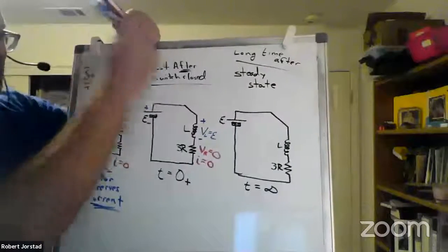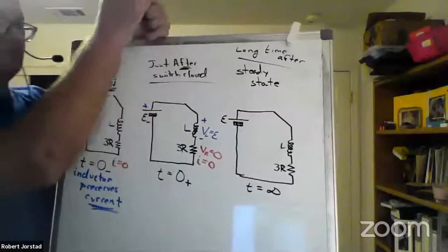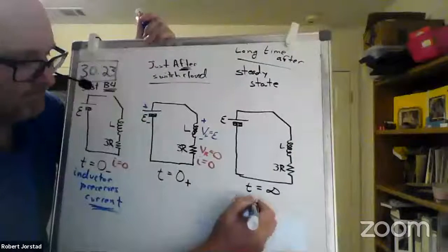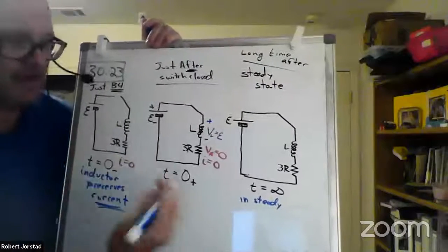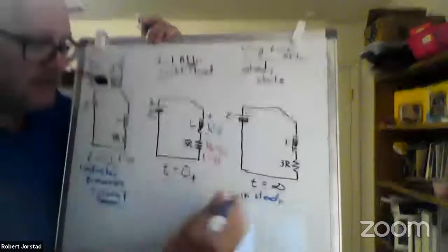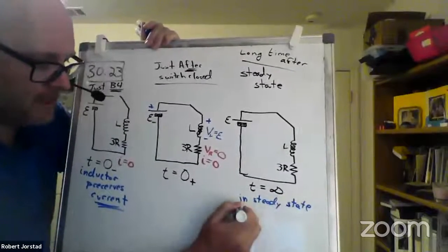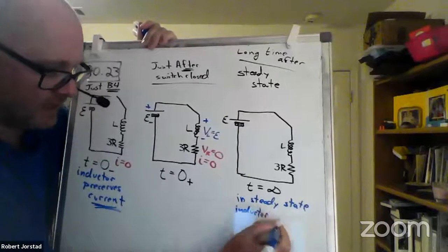All right. Then what's the next step? In the T equals infinity picture, what are you supposed to remember? The voltage across the inductor is 0, or the current across the inductor is 0. Yeah, I would go with that because with inductors, it's good to start with current. I think you're right in this case, but in steady state, I would start with the inductor. This is the reasoning I like to use.